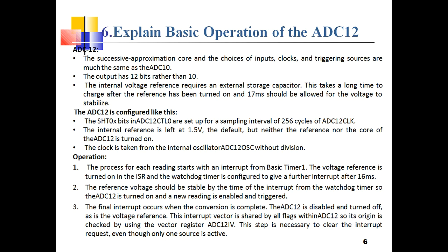Then how is it going to perform the operations? The process for each reading starts with an interrupt from Basic Timer 1. The voltage reference is turned on in the ISR, and the watchdog timer is configured to give further interrupts after 16 milliseconds.